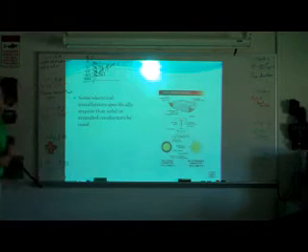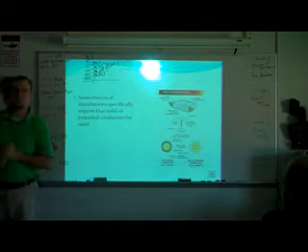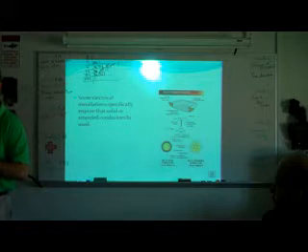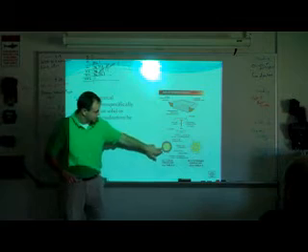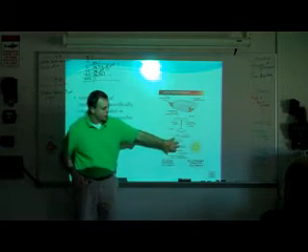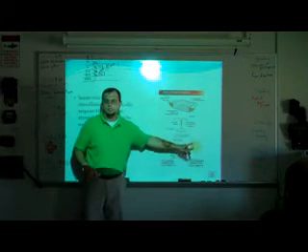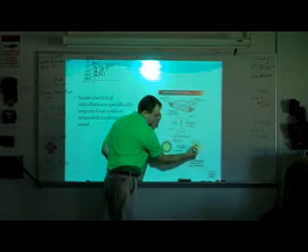Some electrical installations specifically require that solid or stranded conductors be used. Stranded or solid, which one is smaller in diameter? Solid is smaller. Because if we look at this, here's our solid conductor, here's our stranded conductor. If they were both 12 gauge wire, this one would actually be bigger, because of these little air gaps right in here.